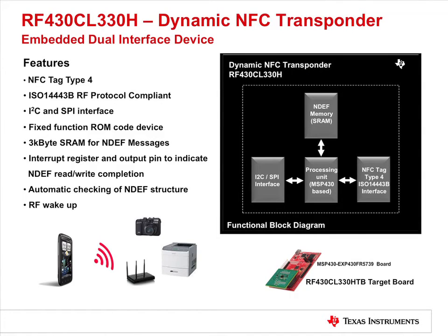Now let's have a look into the dynamic tag, the RF430CL330H. The Texas Instruments Dynamic NFC Transponder, RF430CL330H, is an NFC tag type 4B device which combines a wireless NFC interface and a wired SPI or I2C interface to connect the device to a host.